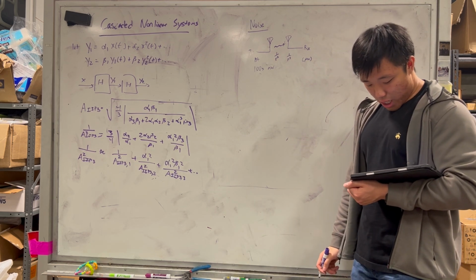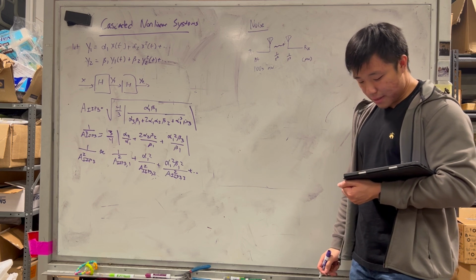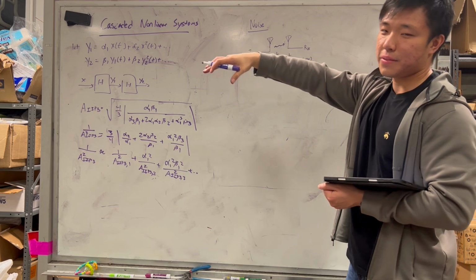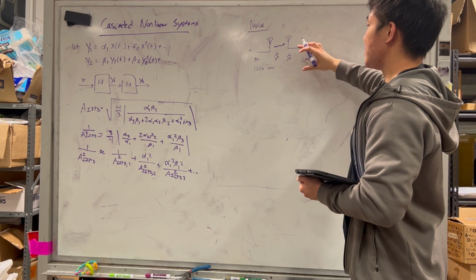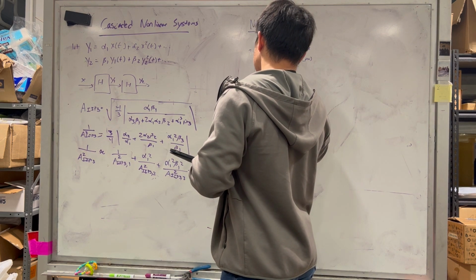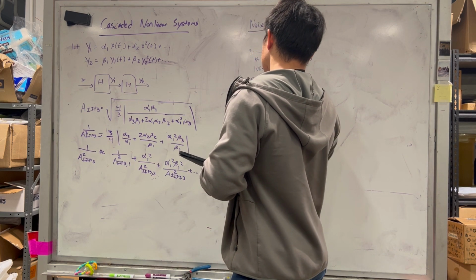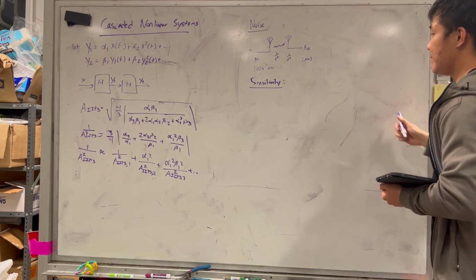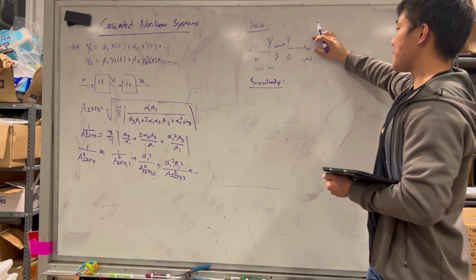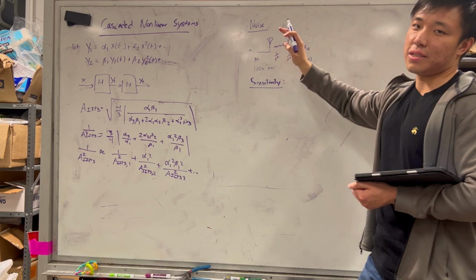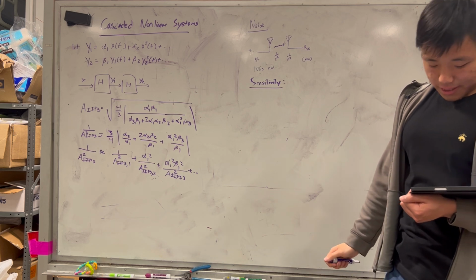And so for practical purposes, your receiver, there's going to be some noise in the channel as well, right? There needs to be some, what we like to call sensitivity. This is a figure of merit for your receiver. It basically describes how sensitive this receiver needs to be to detect your desired signal of interest.